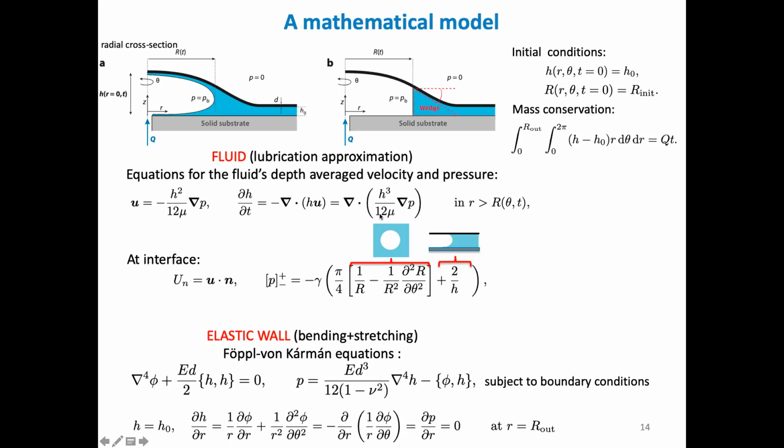So it's a fluid structure interaction problem, and the liquid pressure changes as the configuration of the setup changes as well. That's sort of a first source of nonlinearity, if you want, in our system. We also have to have some boundary conditions at the interface. This one is just the kinematic boundary condition, saying at which speed the interface expands.